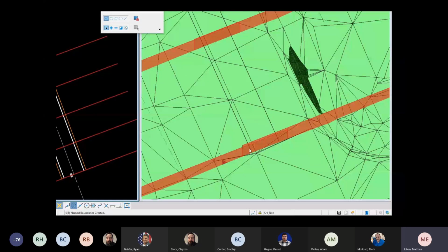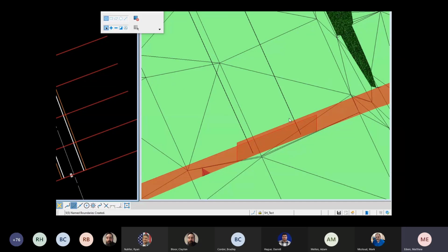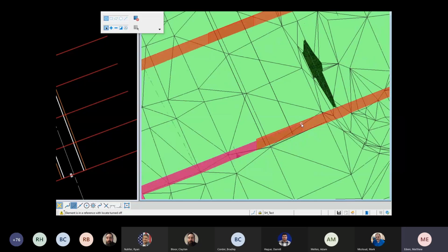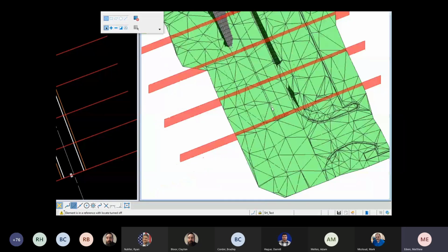As I mentioned earlier, you can see the height difference here and how the software determines the top elevation of the name boundary. When I snap to the one that was created on the right, it's at an elevation of 1202.14. If I snap to the one for the left, it's at 1200.12. So you may decide you want to make those all the same so that each sheet matches. That probably could be an enhancement to the software that we could submit. And then on the lower end, it looks like for the most part that would probably be the same.